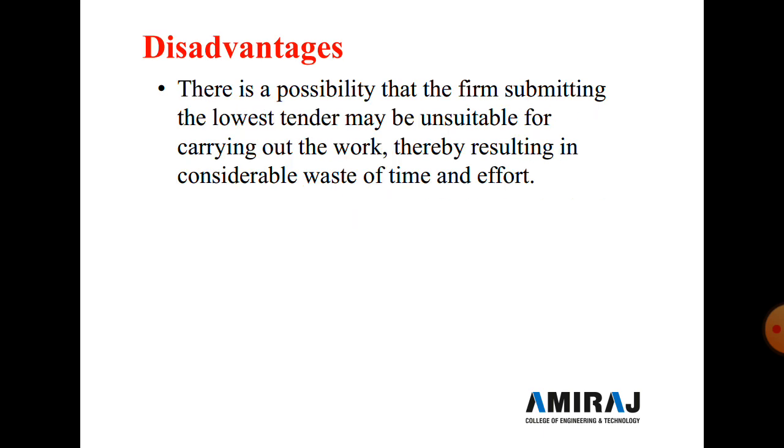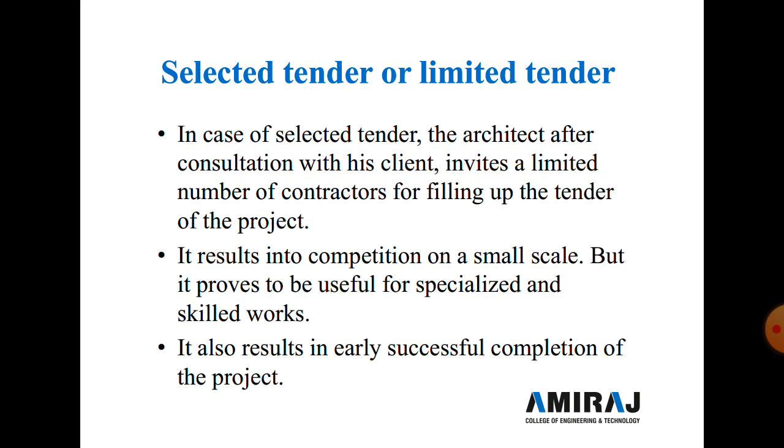And there are also some disadvantages. There is a possibility that the firm submitting the lowest tender may be unsuitable for carrying out the work, thereby resulting in considerable waste of time and effort. So these are the disadvantages of open tender.